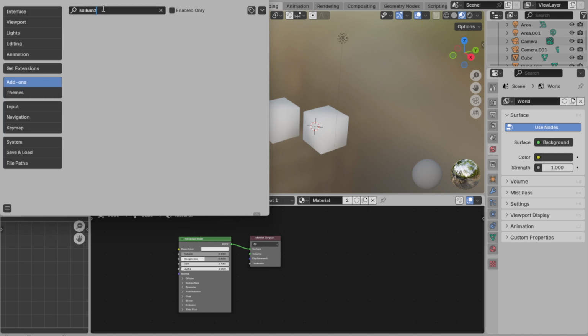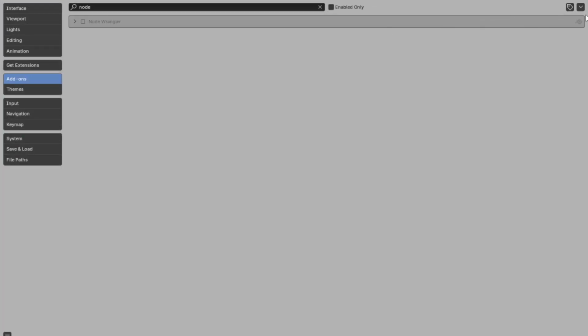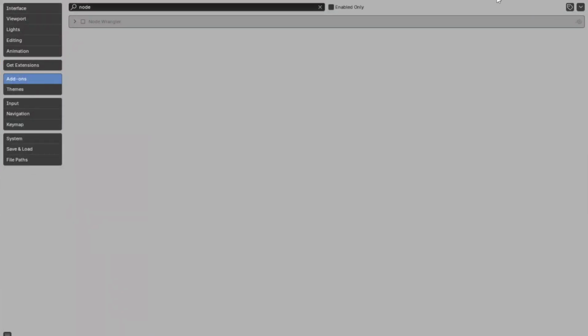This tool provides a major shortcut. With the Principled BSDF node selected, use the combination Ctrl, Shift, and T. This keyboard shortcut opens up the file browser where you can select all your relevant texture files at once. Once selected, click on Principled Texture Setup. This will automatically connect your chosen textures to the correct inputs on the Principled BSDF node, beautifully organizing your node setup and making sure each map is placed where it belongs.